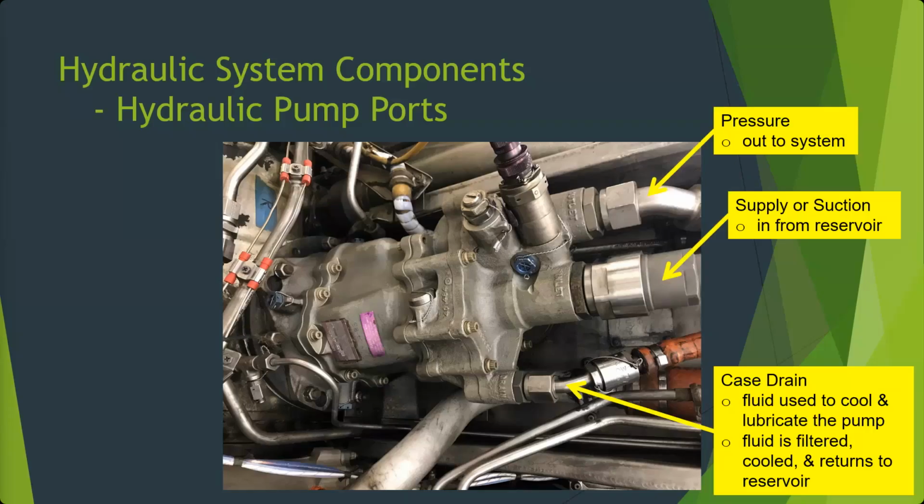It's all the same. So the fluid, the inlet here comes in. Most of it's going to get sent back out the pressure side. Some of it's going to provide the lubricating and cooling and then come out the case drain port. Yeah, so there isn't a separate coolant. It's all the same hydraulic fluid that you're using for both cooling and lubrication, as well as pressure.